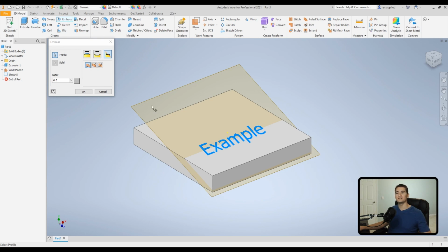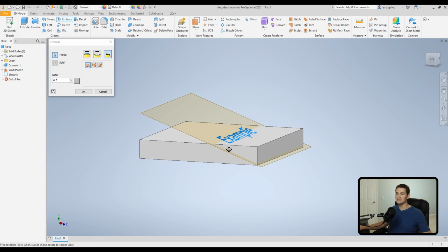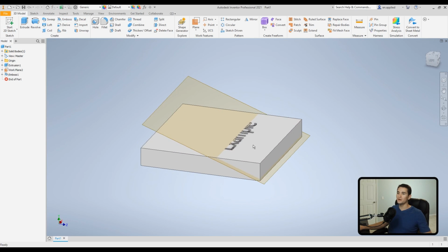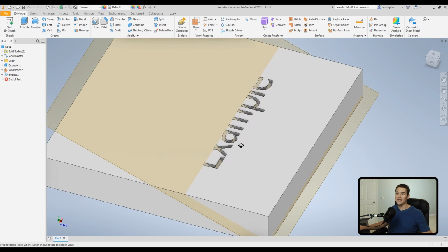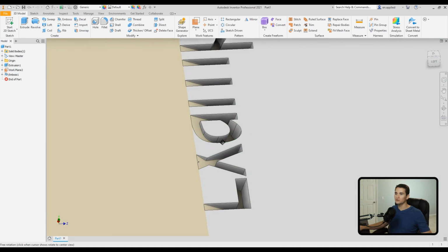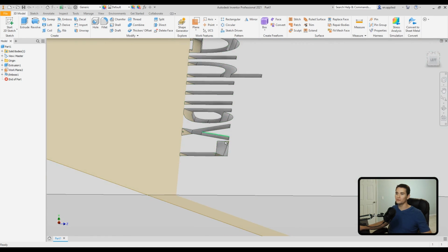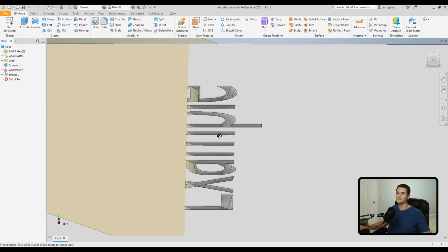The first command is our first direction, and so you see the arrow pointing up. So let's just go ahead and click OK and see what happens. So you'll notice what happened was the text that resides on the plane below the surface going upwards towards the top surface of the solid body, it created an engrave on an angle there. So if we look a little bit closer, you'll see there's an actual angle to each one of these letters.